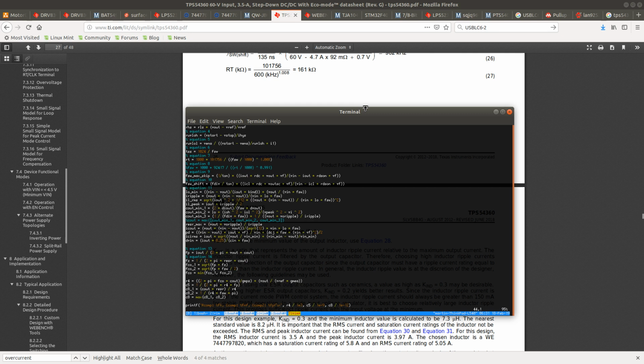So this is not a simple thing to do. This is not like an LDO regulator where you just fit 2 resistors and you get your output voltage. This is a much more advanced regulator, but the benefit is that it's also very flexible. It can be used to, for example, produce split rail power supplies, and you have control over a lot of different parameters, which can be useful sometimes. And also it can go to much higher frequencies than the cheapest regulators. So the ripple on the output becomes a lot smaller as the frequency rises.